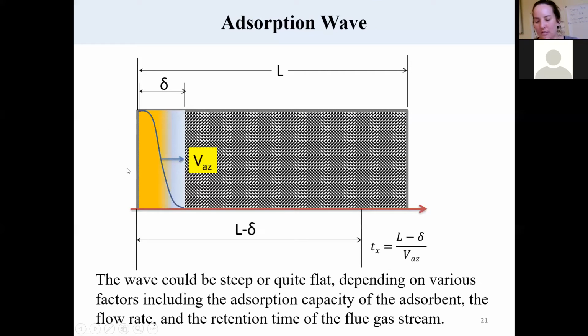This happens at the beginning when the polluted gas stream starts coming into the filter, and pretty soon all of the sites at the beginning are going to get filled up. After this happens, this whole part where the concentration decreases from 1 to 0 is simply going to shift to the right, and it's going to keep doing that. The steepness of this curve will always be the same; it depends on the flow rate.